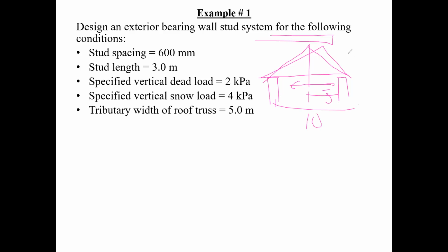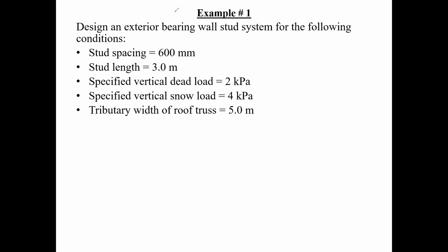And now my snow load that's coming down here is 2.4 kPa. I'm sorry, the dead load of the roof is 2.4 kPa, which is pretty high compared to the snow load, but it doesn't matter. It's just an example. So now the specified wind pressure, 0.883.